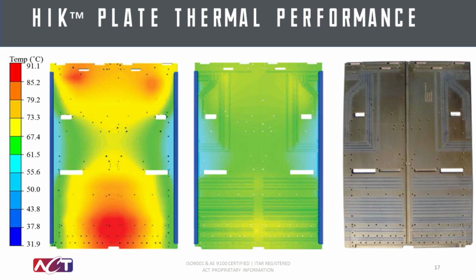On this next slide, we're looking at a plate that was designed for an application in which it was edge-cooled. So in the thermal charts on the left side of here, you see blue lines. The boundary condition is that these are locked into a liquid-cooled rail held at 32C. Even with those rails held at 32C, on the very left image, which is all aluminum, you can see the three devices that were creating local hotspots on this plate.